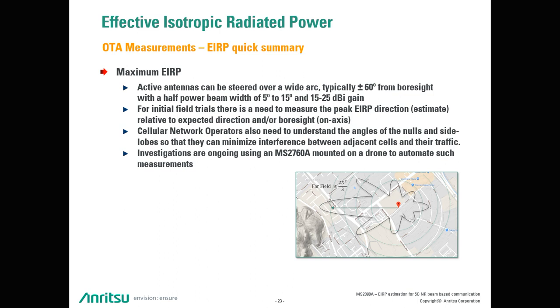Operators also need to understand the angles of the nulls and the side lobes so that they can minimize interference between adjacent cells and their traffic. Investigations are ongoing at the moment using an Anritsu MS2090A ultra-portable spectrum analyzer on a drone to automate such measurements.